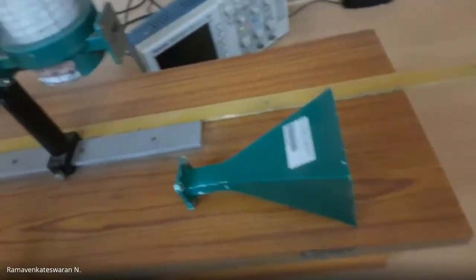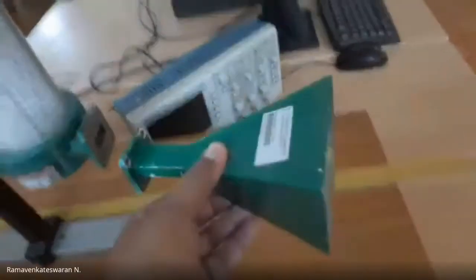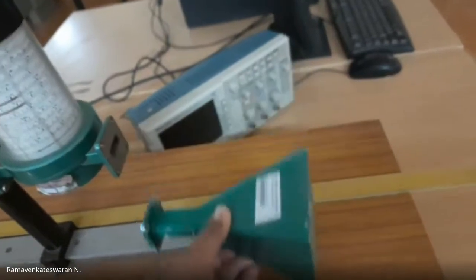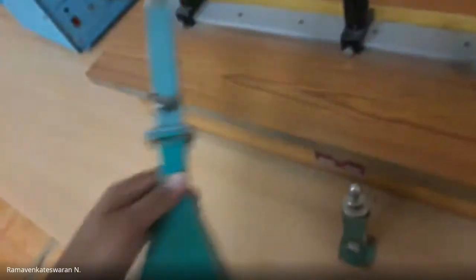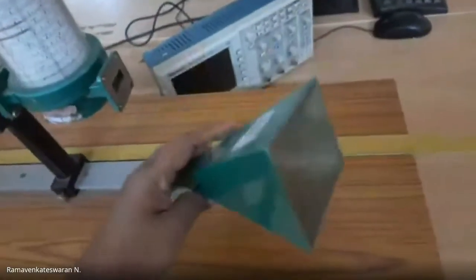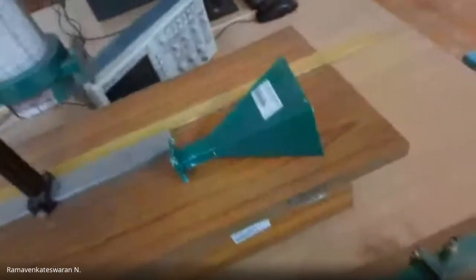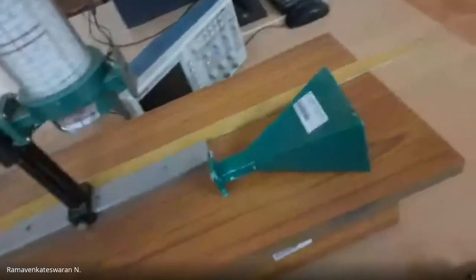Generally in the experiment, I have a test bench with an antenna connected here. This is transmitting, and on the receiver side, I have another antenna to receive. I again have a crystal detector with a coaxial mount, and this will be connected to the oscilloscope. So I can find out how much power is transmitted and received, and I can measure the gain of this antenna. However I've done the simulations and the design, practically I can measure what the gain is. So these are normally the setups.